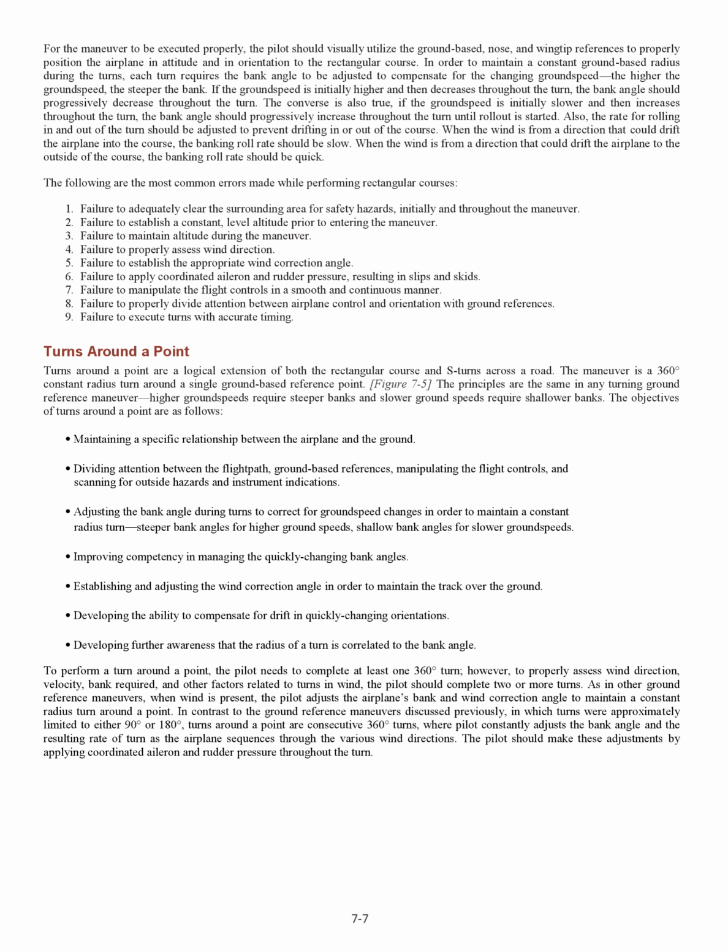In contrast to the ground reference maneuvers discussed previously, in which turns were approximately limited to either 90 degrees or 180 degrees, turns around a point are consecutive 360 degrees turns, where the pilot constantly adjusts the bank angle and the resulting rate of turn as the airplane sequences through the various wind directions. The pilot should make these adjustments by applying coordinated aileron and rudder pressure throughout the turn.